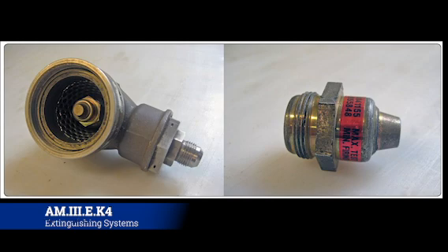Now, that fire suppression agent, now that it's not being held back anymore, will immediately try to leave that bottle, and it goes through the discharge valve, which is on the left-hand side here. You notice that it all of a sudden opens up and allows that agent to start to expand. As it expands, it spreads out. As it spreads out, it hits the fire and removes all the elements that fire needs to keep on going. And so you get that one shot of halon or CO2 or whatever the agent is directly onto the fire, and it puts it out.